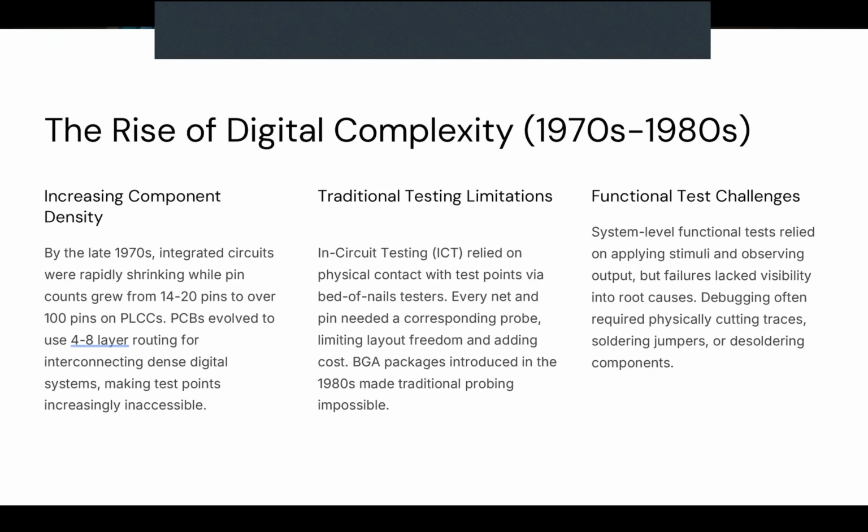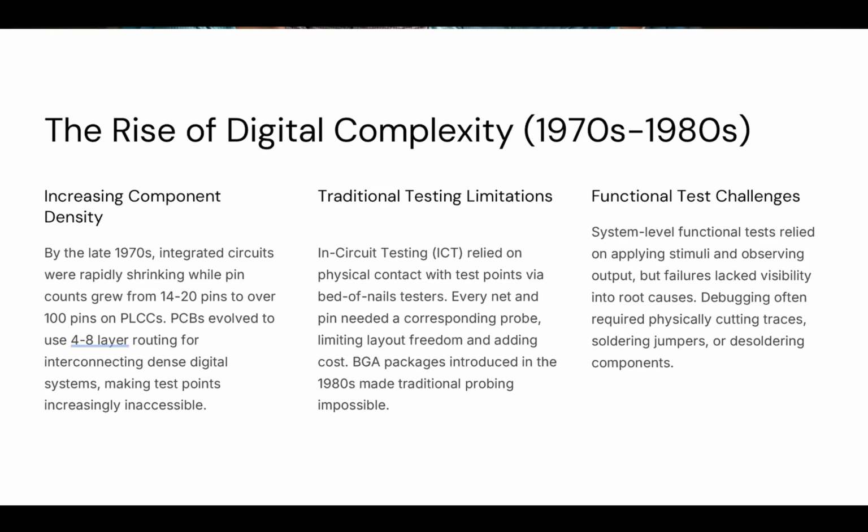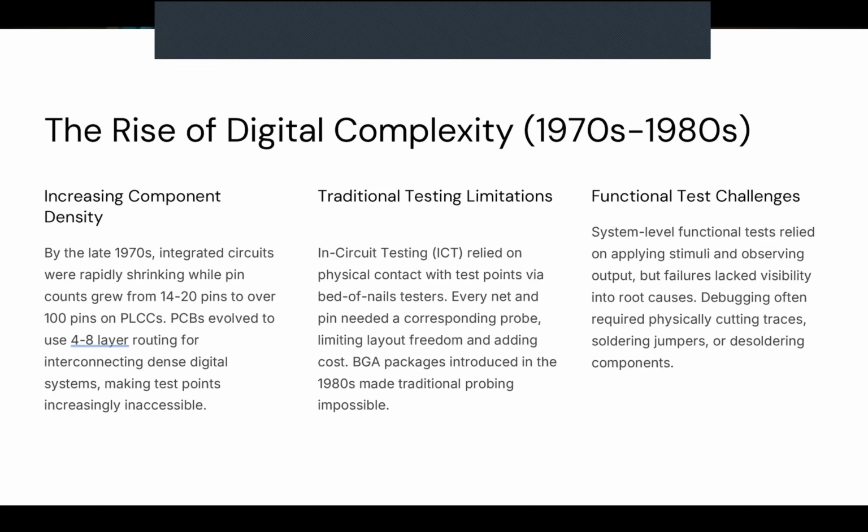That loss of access basically ruled out all the traditional test methods, most of which were based on a bed of nails fixture, oscilloscopes, or a logic analyzer. All of them needed to directly connect to the PCB traces or the component pins.